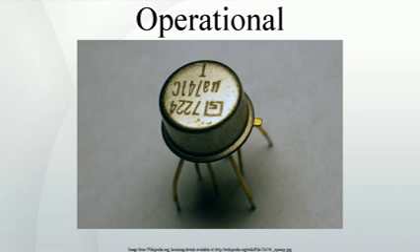The 25 ohm resistor at the Q14 emitter, along with Q17, acts to limit Q14 current to about 25 mA. Otherwise, Q17 conducts no current. Current limiting for Q20 is performed in the voltage gain stage. Q22 senses the voltage across Q19's emitter resistor, 50 ohm. As it turns on, it diminishes the drive current to Q15 base. Later versions of this amplifier schematic may show a somewhat different method of output current limiting.